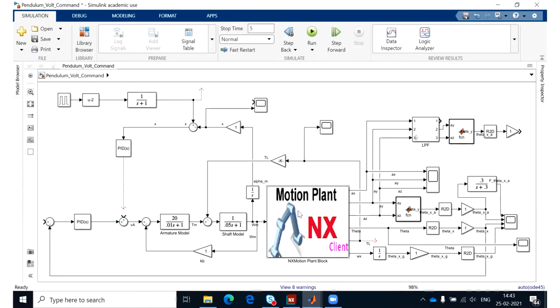we have changed the size of the pendulum a couple of times and also the weight. So I didn't actually look into what motor we should select and what torque, for example, we need, but you should do that. Because in the NX model, you can decide what the weight and the dimension of the pendulum are. And when you do that, you can decide what motor you are going to use. And when you have the motor type, you can go to the data sheet and find these parameters, and you're going to have the model of the motor.